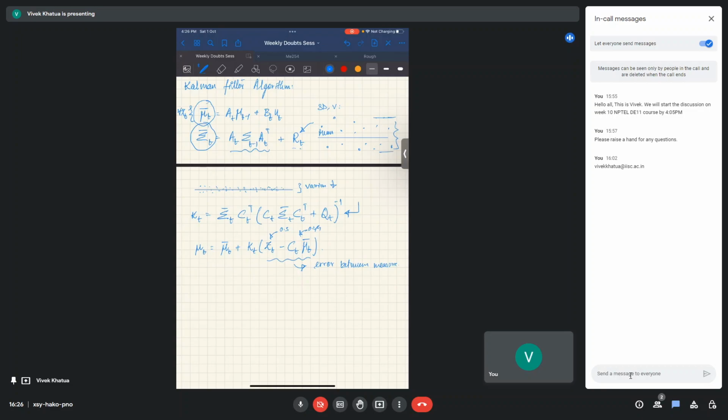That error is multiplied with Kalman gain. Now, if the Kalman gain is high, such errors will be magnified, and that will be adding up to your state. If this error is low but Kalman gain is high, it's not going to be contributing in your state. And if the Kalman gain is low, regardless of your error, if you see how your Kalman gain is made, it is made out of your measurement model.